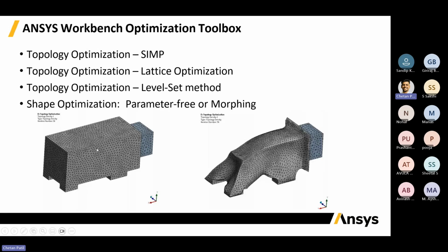And then over here, you can even set constraints. Like you can see whatever the shape of this geometry is, for how much distance or how much elemental displacement should be allowed for the morphing process, that is, for a change in the shape of the elements or the displacement of one of the edges of the geometry. Those kinds of things can be used as constraints to morph your geometry under whatever conditions you are using it for.